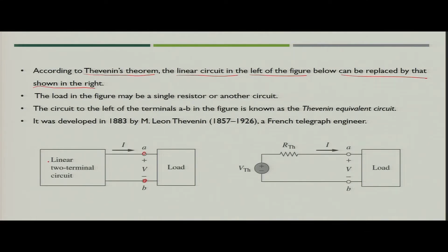Keep in mind that Thevenin's theorem works well when the circuit is linear. So, you assume that the circuit outside your plug point is a linear circuit, and you replace that segment with one equivalent circuit with one voltage source and one resistance.